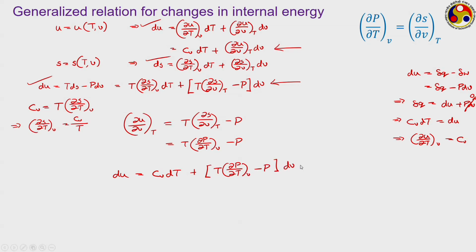Look at the left hand side, here we are talking about the changes in specific internal energy, whereas on the right hand side, we have specific heat at constant volume, Cv, and we only have temperature, pressure and specific volume. So, if we know the PVT relationship of any particular substance, something like an equation of state, ideal gas equation of state, etc., you can easily calculate the changes in internal energy using that knowledge and also the knowledge of this Cv.